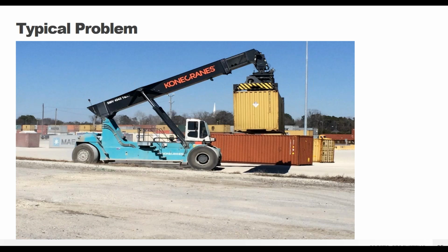This is another typical problem that we see. This is going to be at things like material handling yards when you have really heavy loads such as containers and reach stackers, which are going to have a much stronger ground pressure than a typical vehicle would. These tend to really tear up aggregate surfaces. It requires a lot of routine maintenance to make sure that you can drive through them, that they can still support the containers, all that stuff.